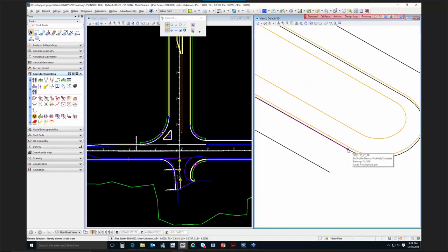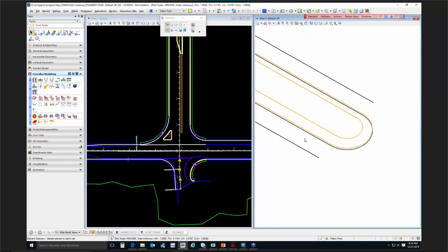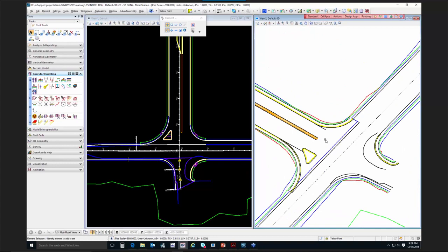Essentially 0.01 feet is good enough, and that's so infinitesimal. It's only so that when it goes to create a top mesh of this or a final DTM, it doesn't go from this line to the top line. It's actually going to go across here and then go up and then across, but it won't be a true vertical surface. It will have a very high slope on it, but essentially it's almost vertical. That's some of the things you want to look at.